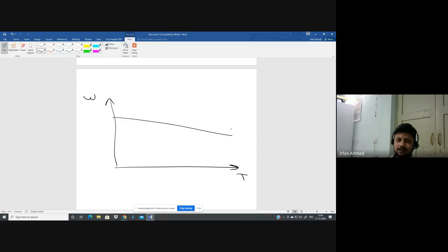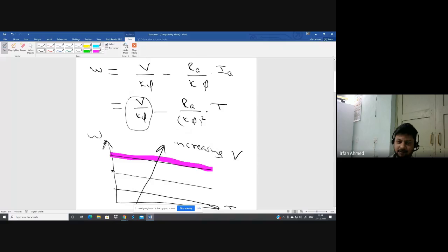And the advantage is that the flux here is in the denominator. So for going above the rated speed, we do not have to increase the flux, we have to decrease the flux. And when it was at rated flux, the field winding was already supplied with the rated voltage. That is why this field flux method cannot be used to obtain speed below the rated speed.